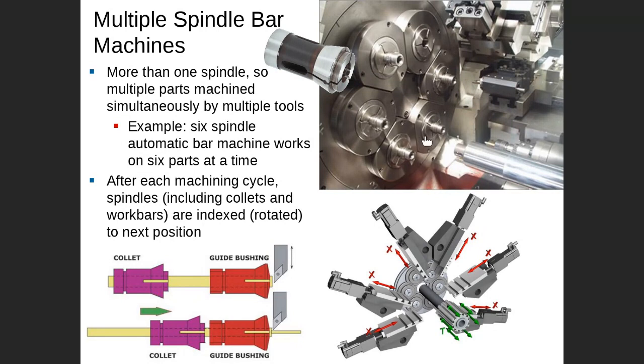Actually, this one indexes, rotating. This one rotates. This is a collet mechanism. Let me tell you, this is a collet mechanism. This is a pneumatic system here. This is a workpiece. We're feeding a workpiece. This one we push like this to feed, or to clamp and unclamp. So we push to open, and clamp to feed the workpiece.